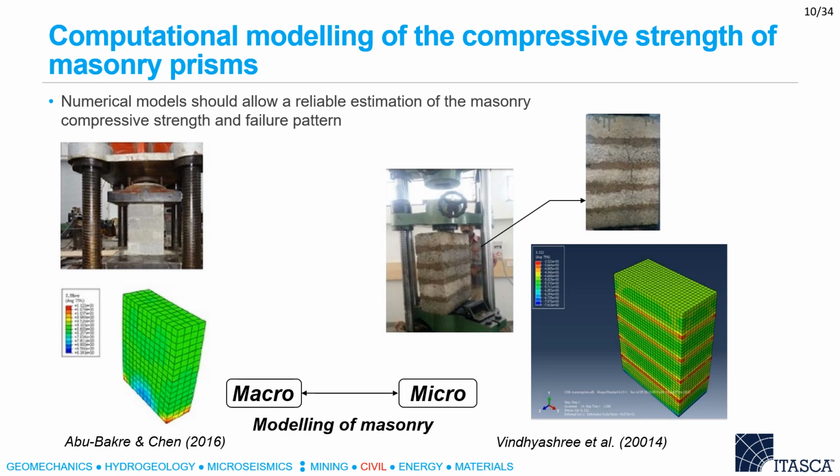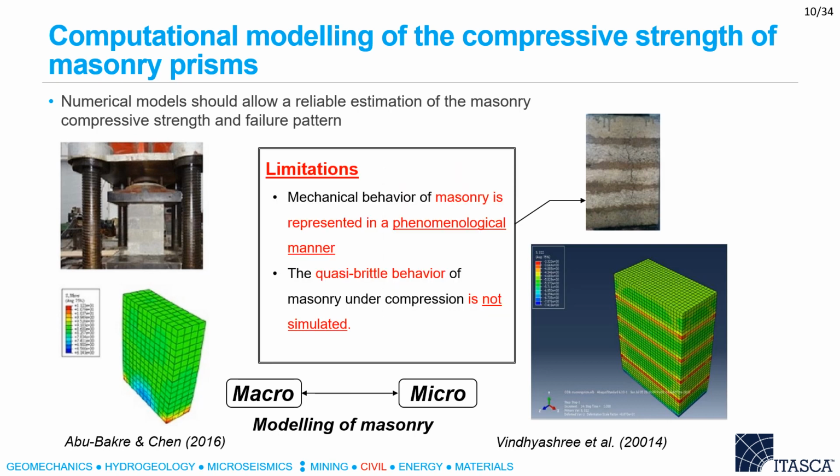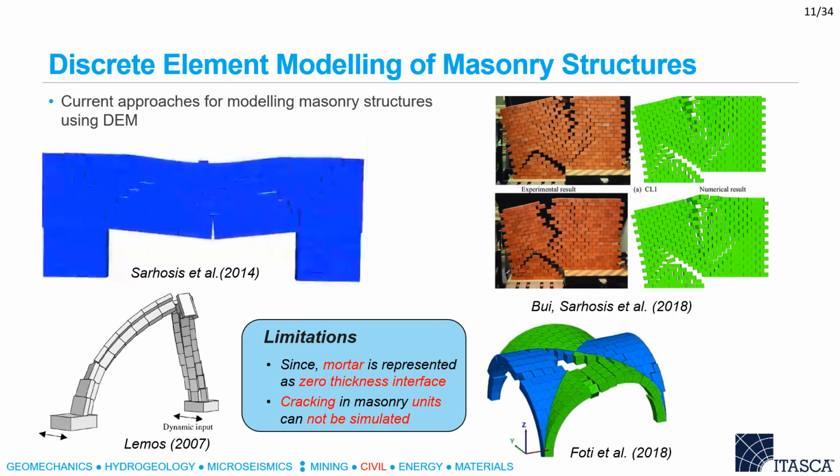However, the currently available models based on macro and micro modeling are able to represent masonry failure only in a phenomenological manner. In this way, the quasi-brittle behavior of masonry cannot be simulated. Similarly, currently developed computational models based on DEM are able to represent failure at the brick-mortar interface or mortar itself rather than the bricks.